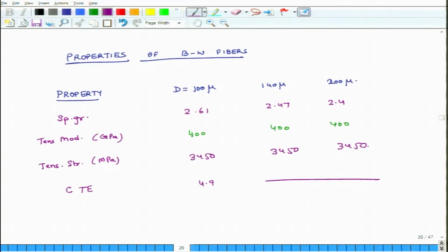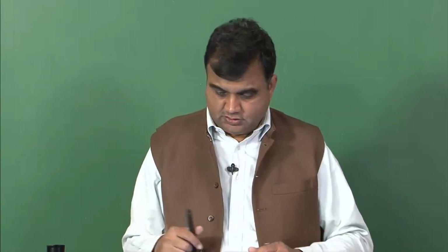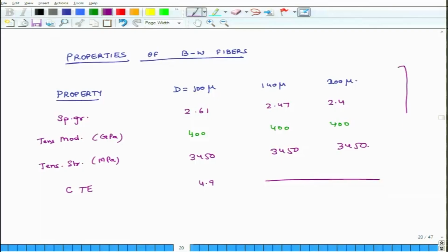But an important thing to remember in case of boron fiber is that it is a composite. So, if you have the core as graphite and outside is boron, boron will expand, graphite will contract. So, there could be high stresses at the interface of these two things, high residual stress in the boron itself, okay, in the boron fiber itself. So, those are some of the important considerations to think about when you are working with these kind of fibers.